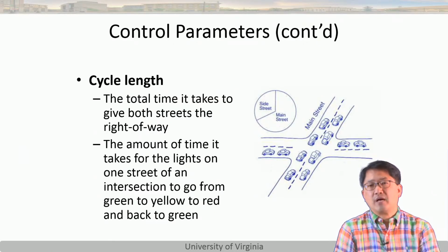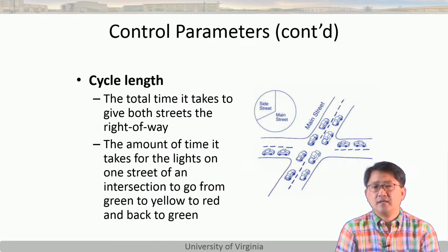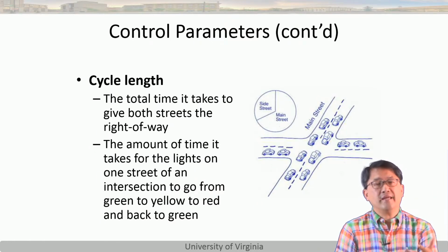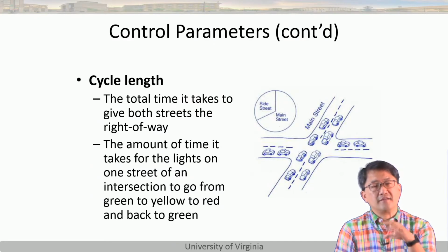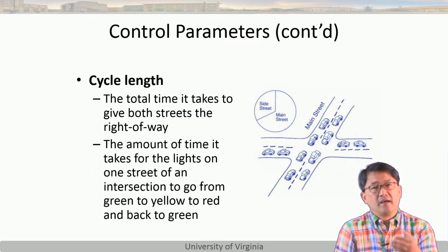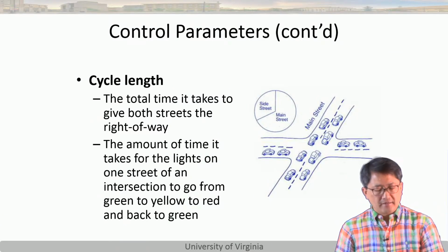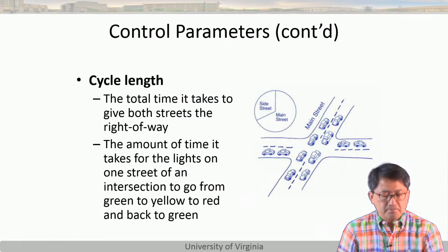And this is also going to be a problem for emergency vehicle preemptions. I don't know how much of this is in India. When fire trucks and ambulances approach, they can actually request green at the intersection. And usually in the US, once you complete the so-called minimum green time, you open up green time for whoever is requesting these preemptions. This actually helps save lives, and it's very good, but it is disrupting the progression as well. So that's a challenge that needs to be addressed well.